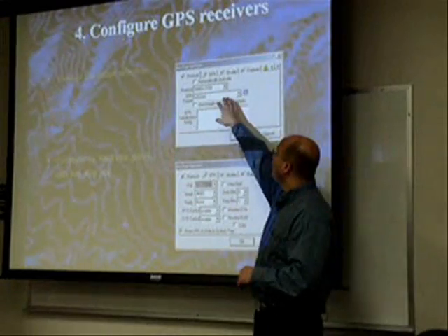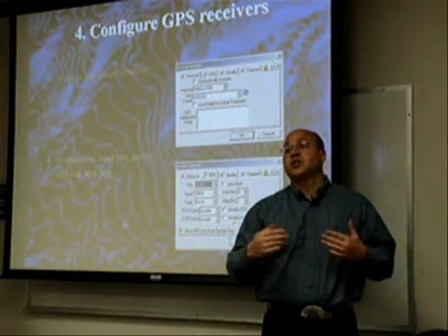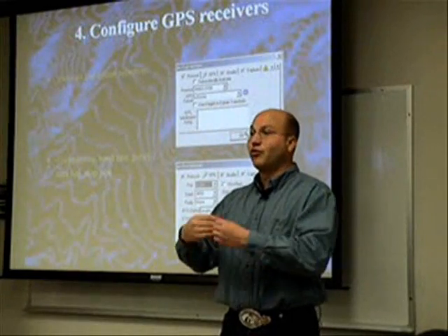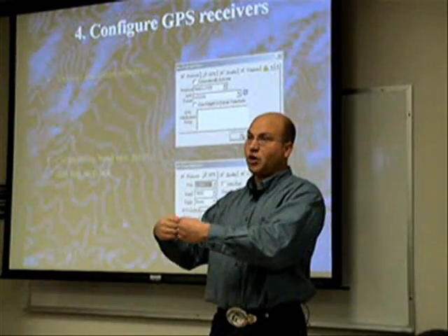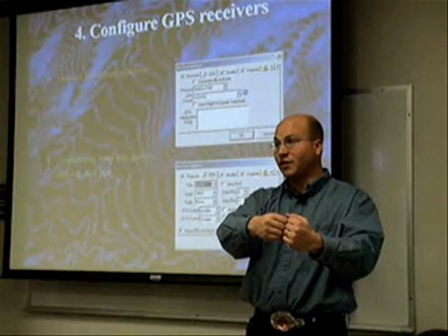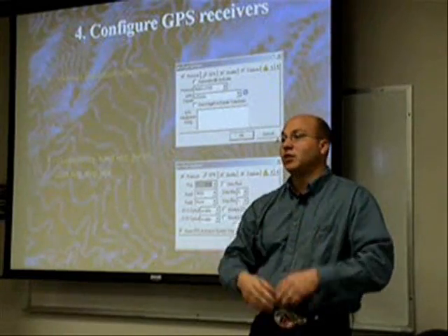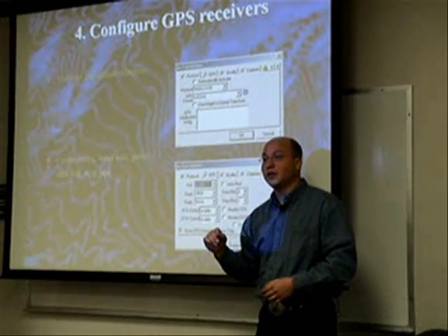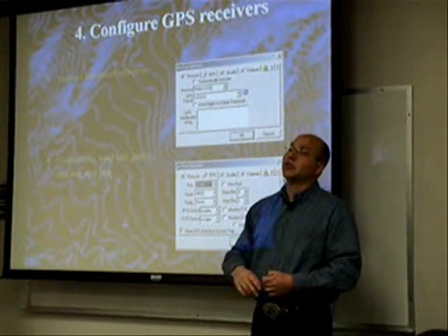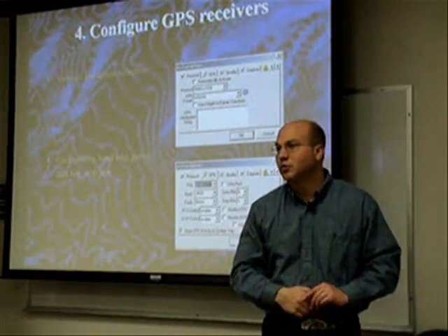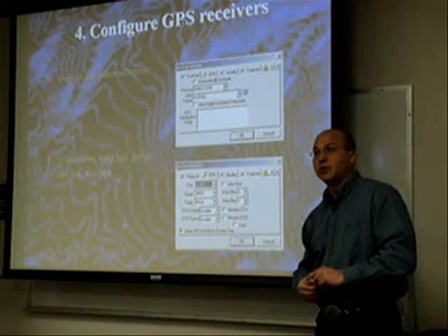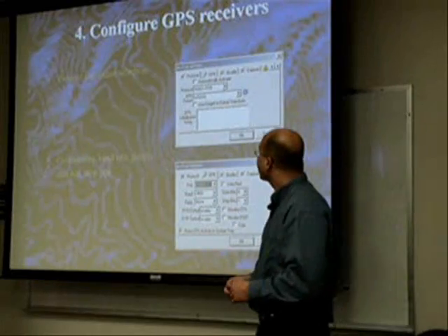Whenever you select a different datum here, you use the specific software's coordinate transformations to go from WGS84 to whatever you specified. So here, word of caution, not all transformation programs are perfect. So a good idea is always to collect in WGS84 to avoid any of the software-specific transformation issues.